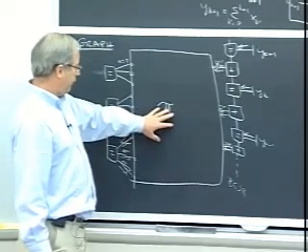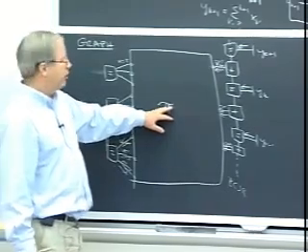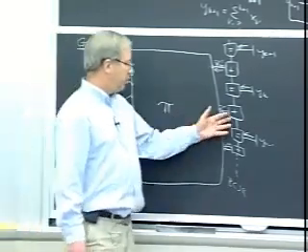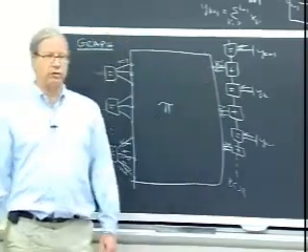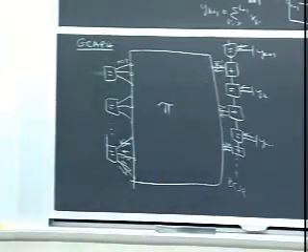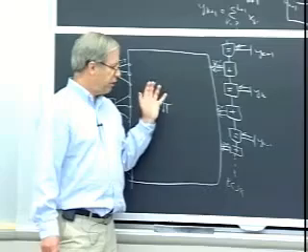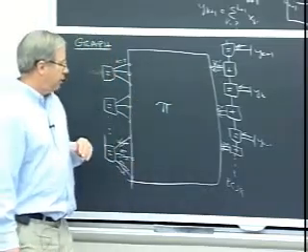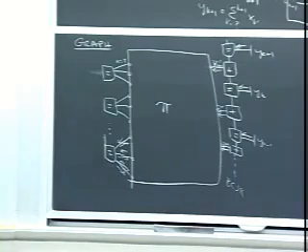Okay, that's the important part of the code construction, but then the decoding part is this, the power is the sum product algorithm used in an iterative way. The idea that you can simply let this algorithm run, and if the code is properly designed, it will eventually integrate all the information over the block and converge to some fixed point.